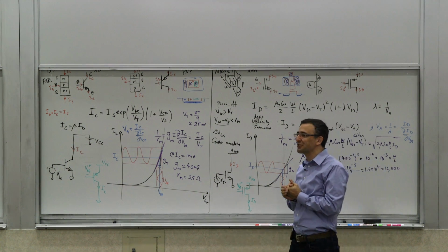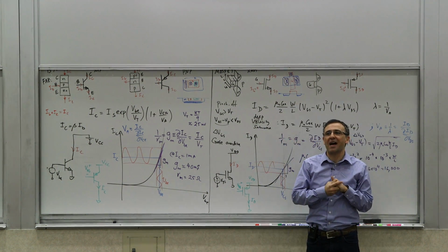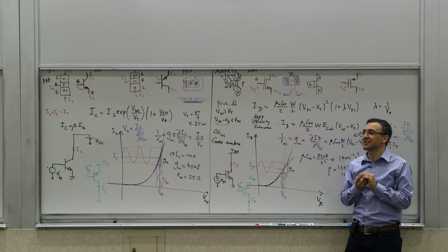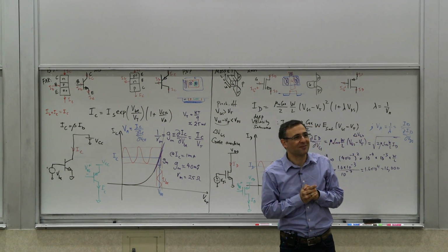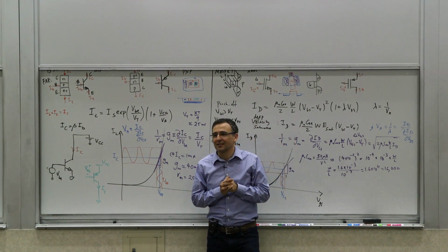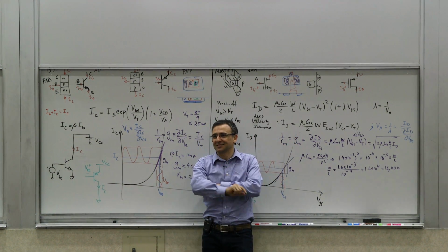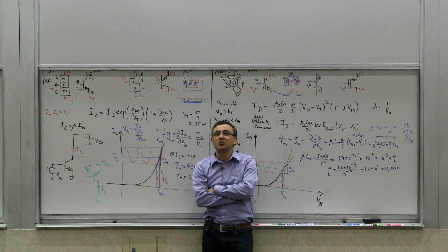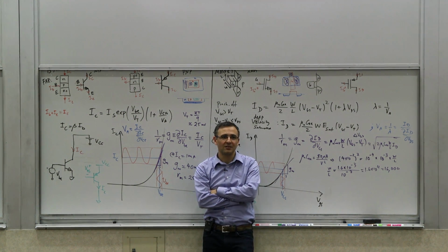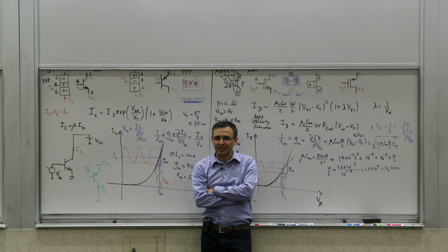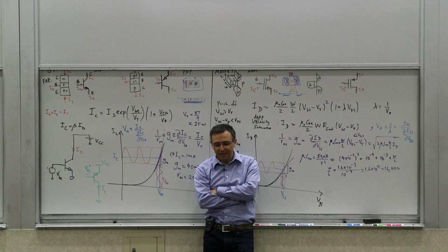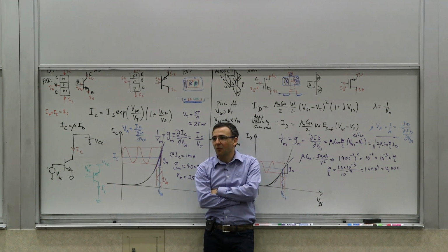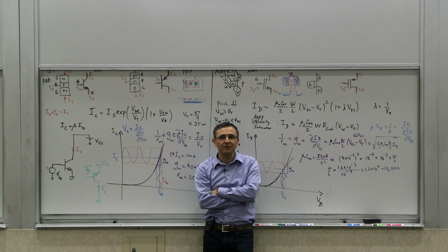There's something really great about MOSFETs that I kind of swept under the carpet when I was talking about this. There are really two great things about them. But yes, go ahead. Small gate current. Small gate current, that's one, right? So you don't need to provide that gate current, and you will see that that matters. There's also another thing that really matters about MOSFETs, and it helps significantly, is that turning MOSFETs on and off is equally easy.